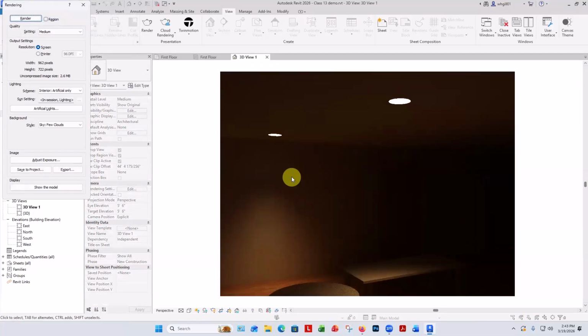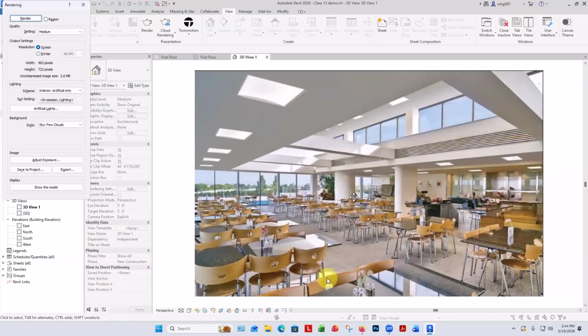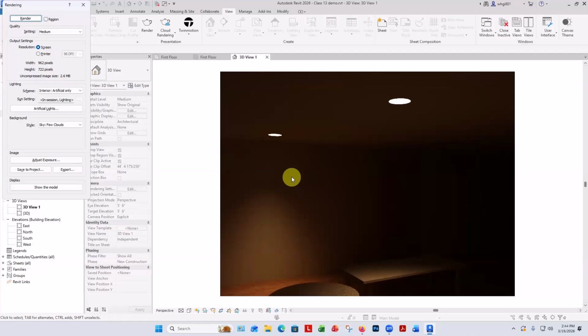Not too impressive. When you're lighting a space, the question is, to get it adequately lit, how many fixtures do I need and how bright do they need to be? I noticed in the ones that Mollie had, I think it was the first picture she showed of a high school cafeteria, it looked like they were those 2x2 bright fluorescent fixtures, maybe every 8 feet or something, which seemed to be balancing the daylight and all. I don't know what their actual light output was. For us, to some extent, this is going to be a matter of trial and error to see what we want to get. I would like to have the sense that this fixture right next to the wall is a lot brighter than that.